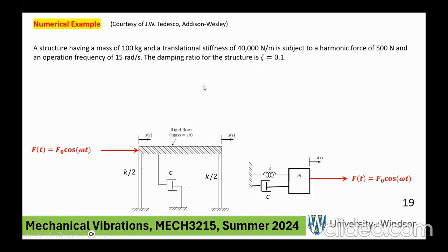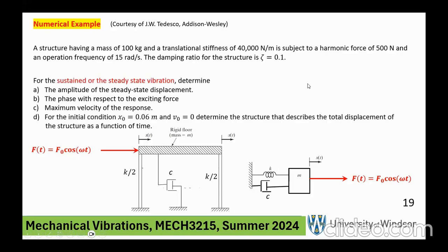Remember, this is a single degree of freedom. You can estimate the damping by logarithmic decrement. And remember how it was: you let it vibrate, plot something, and out of that something, get the logarithmic decrement. So we did it and came up with 0.1, or somebody has done it for us. Okay.